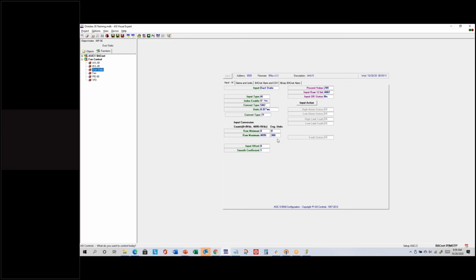And so our controllers themselves, since we don't have any wiring connected to them, the pull-up resistor is in place, which is fine. In the live training class, we would normally connect a potentiometer to the input, and then we can spin the potentiometer to adjust the present value. Since we can't put our hands on the training kits that are remotely accessible, we're just going to end up overriding the input to adjust the values and see how the controller responds.